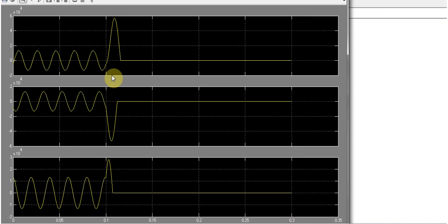You might also have observed that the fault occurs here, and the current is still increasing, and the relay doesn't stop the current until it touches the 0 value. So the relay keeps operating until the value is zeroed, and you have to almost complete the cycle until it reaches the reference value of 0 ampere.